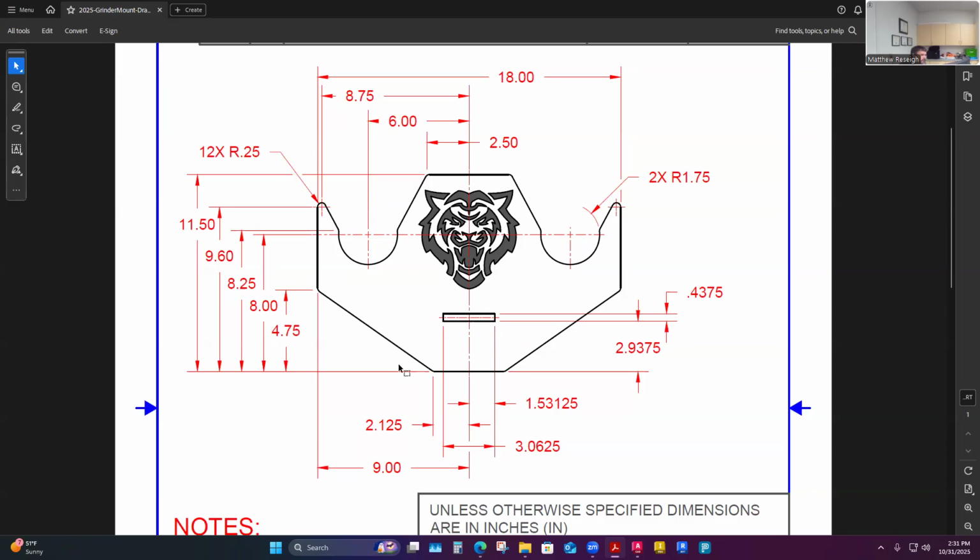But if I was going to build a box out of this, I'm going to keep sharp corners, as in a lot of manufacturing. For here, this is actually a finished part that you're going to be handling. Maybe you pull it off your rig and throw it on your pipe stand, just to hold your grinders there. So this is going to be a part you handle. So I'm just going to detune all those sharp corners so they don't jam my hand when I grab this. It's just going to be kind of comfortable.